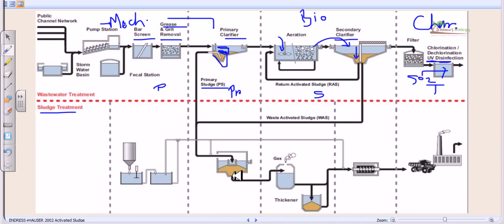Now what we mean by sludge digestion is that we have huge pipes and pumps. We utilize heat, and we utilize a small amount of bacteria which are present in the sludge to digest the sludge anaerobically, and as a result of this anaerobic digestion, they produce methane gas. In this particular process, we utilize a small number of microorganisms which are methanogens.